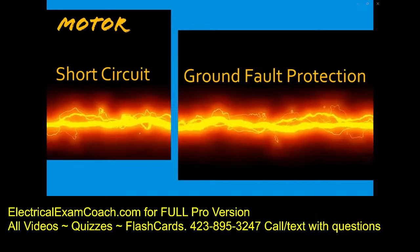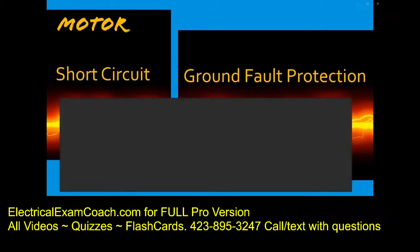There are 2 types of protection for a motor. One of them is called short circuit ground fault protection, and the other one is called overload protection. They are 2 separate things, and they've named them on purpose so you would know what rules to apply. So let's learn about what they both are, and that way we can rightly divide them. And all I want you to think about, so you don't overcomplicate it, is both of these protections are just breakers and fuses. Okay? That is what was so hard for me to understand at the beginning, because you hear these 2 different types of protection and you can really get lost in the sauce. But all they are is breakers and fuses.